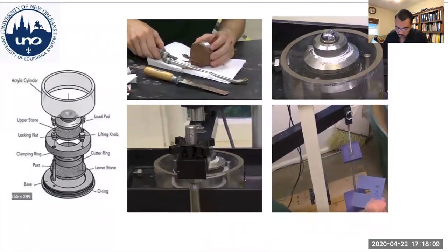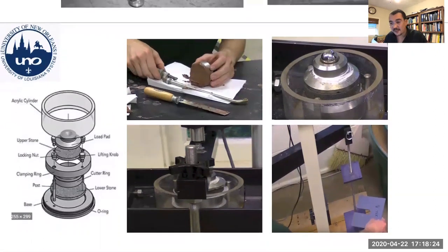And we mentioned also how you can set up this test and how the ring is, and you have a load plate and you keep on changing the loads, and you have to be careful to change the loads very quickly. There's one consolidation meter that is more like a black box.